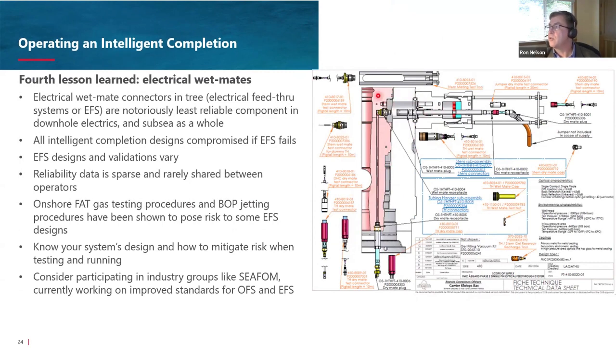I apologize, but this is a drawing of a tubing, with the tubing hanger in red landed in the subsea tree. And basically all your cabling comes from downhole and it comes through the tubing hanger to this connector here. Then on the tree side, there's another connector that mates up with it that's operated by the ROV. After you land the hanger, the ROV basically drives these two together, and you have this connection take place here.